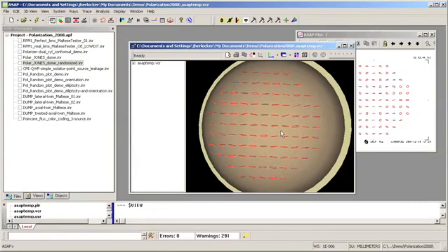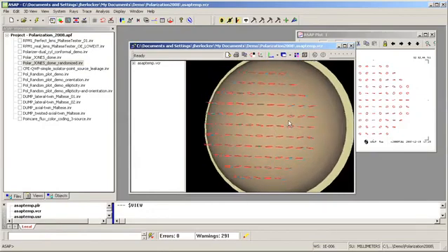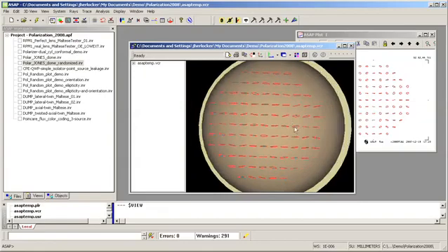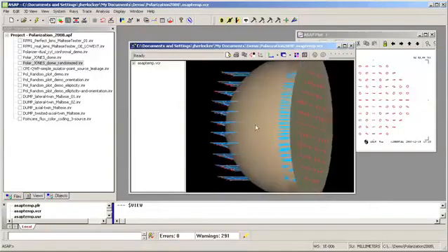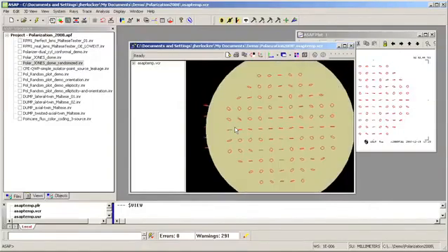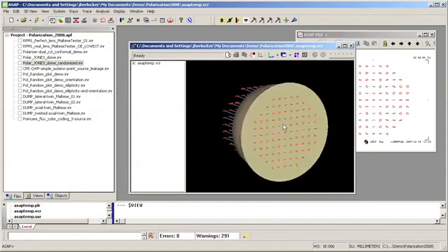There's a slight ellipticity and a slight orientational variation. This is a new feature of sources in ASAP and their polarization support. So we'll see some minor perturbations in the output due to the perturbations in the input. And this is a useful way of simulating non-idealities in a system in the polarization of the source itself.